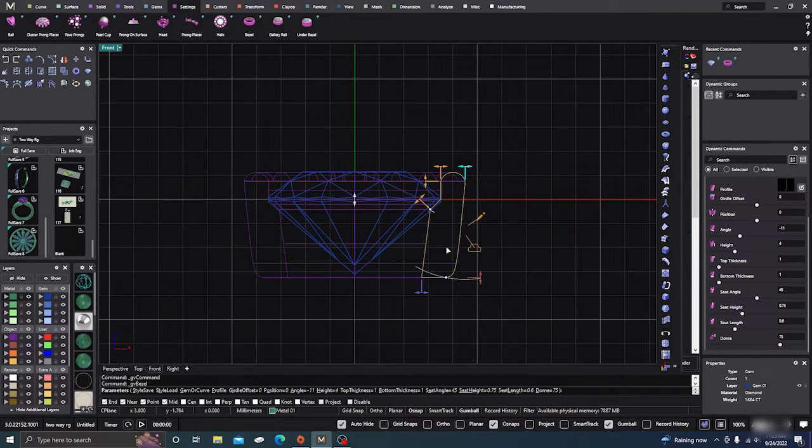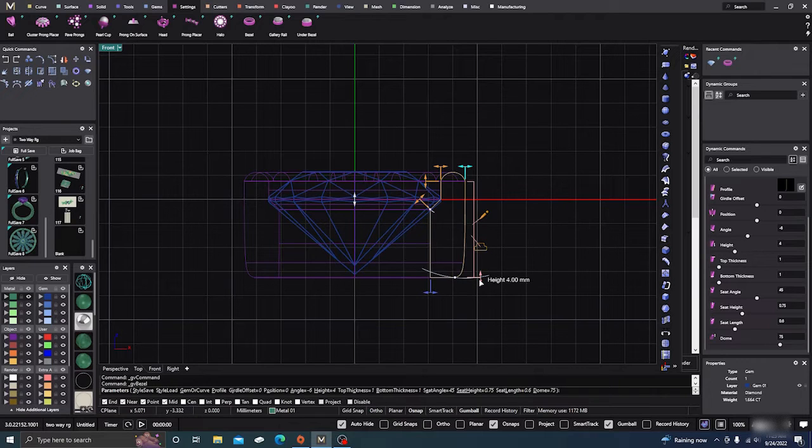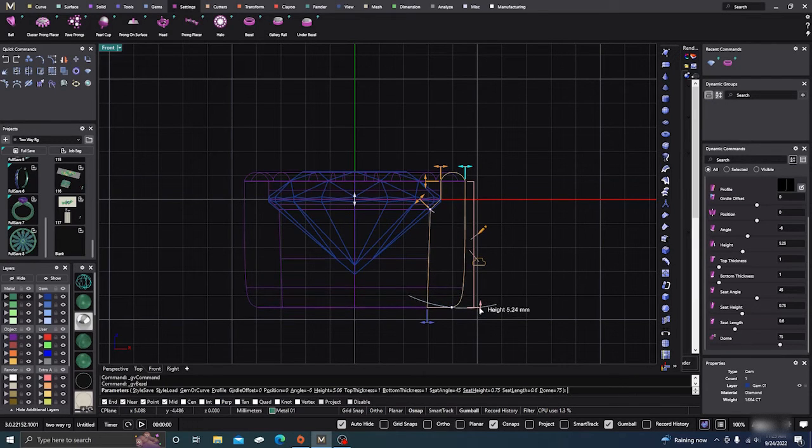Now our cutout will be in this area, so we only have like 1.5 millimeters, because we have to leave a 0.5 millimeter there, and you probably want at least a 0.5 millimeter there. So you want to drag that, oh, wrong one. You want to drag this handle down a little bit, so we'll take it down to a little over 5. Yes, we have a nice area there to do a cutout.